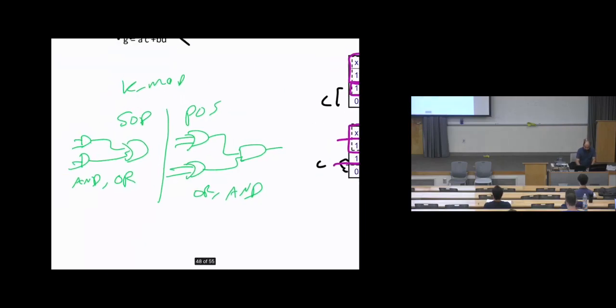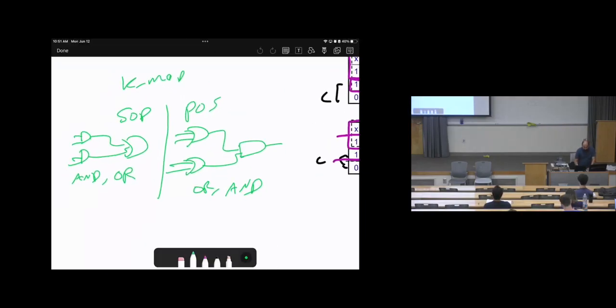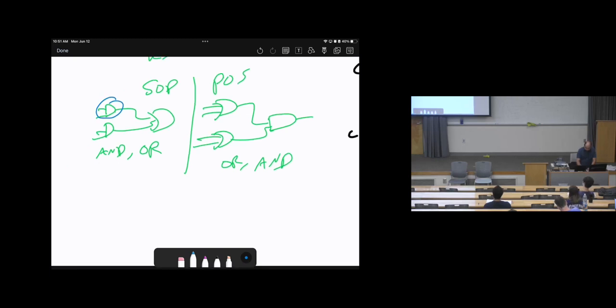Here we need to have AND. But in our real life, in daily life, we have NAND. So what shall we do? Someone can say, I can put NANDs, put NOTs. NANDs, put NOTs. Then here, I can put OR, then put NOTs. Someone can say like this. This is not actually practical. Why? You are increasing the number of gates. 1, 2, 3, 4, 5, 6. And our target is to use as few as possible.